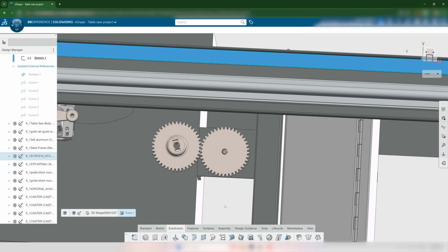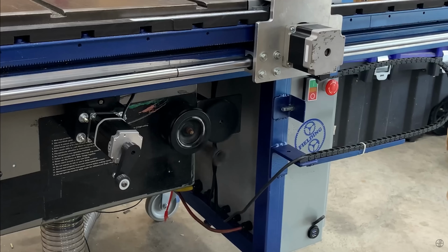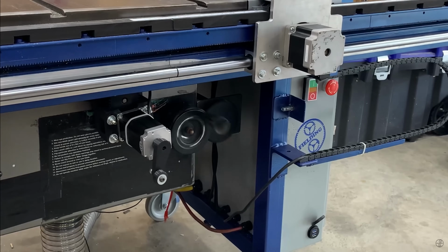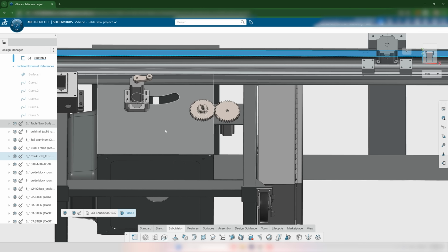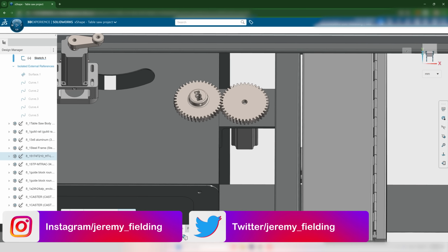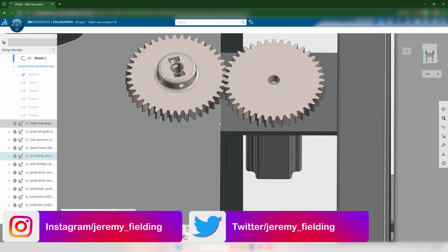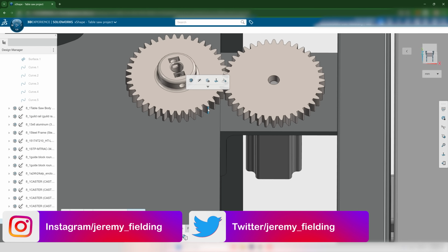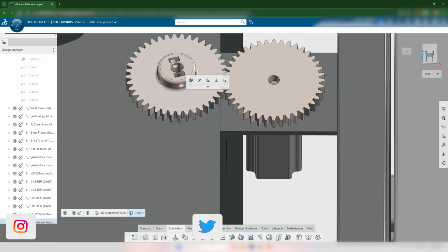Down here, I needed the gears to be strong enough to tilt this mechanism and slide all of that left and right, as well as move the whole motor inside of the system for tilting the blade, because all of that stuff moves together when you tilt the blade. So I used a 1-to-1 gear ratio, but you can see that the teeth here are relatively thick. These are 3D printed gears, but they're printed at 50% infill.